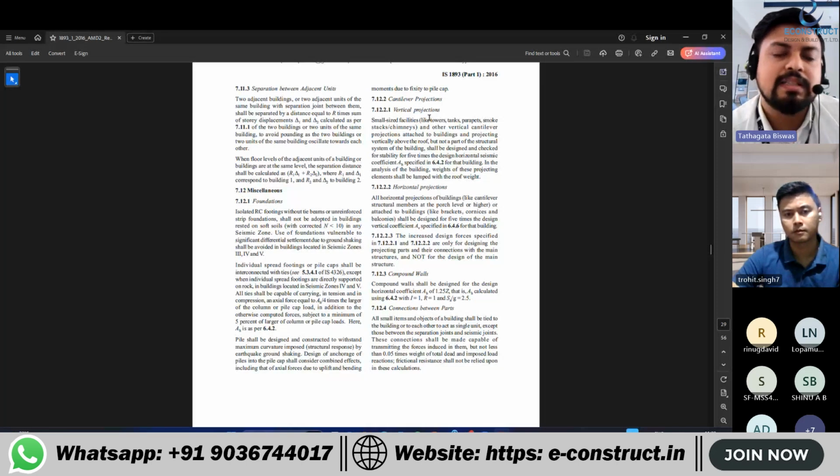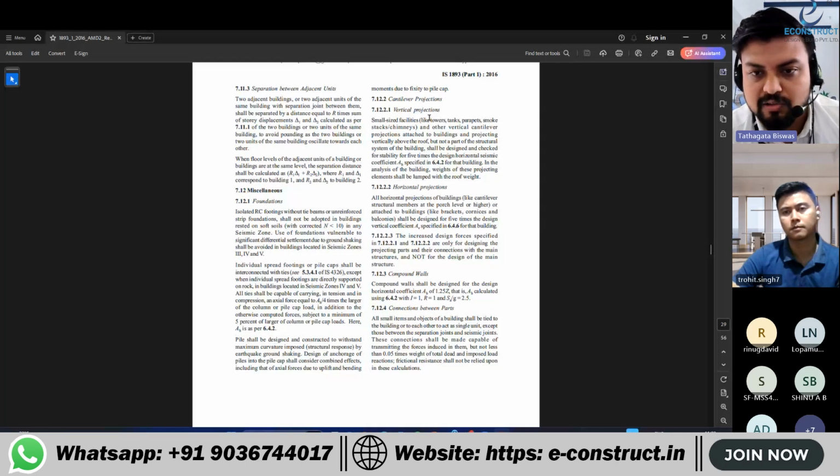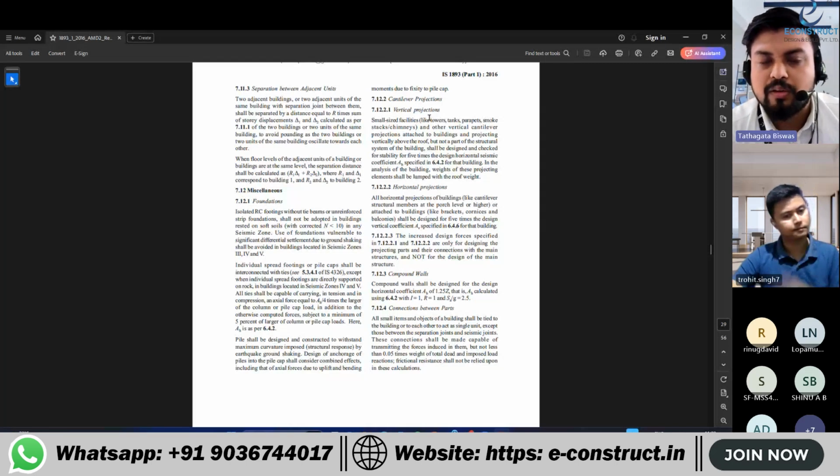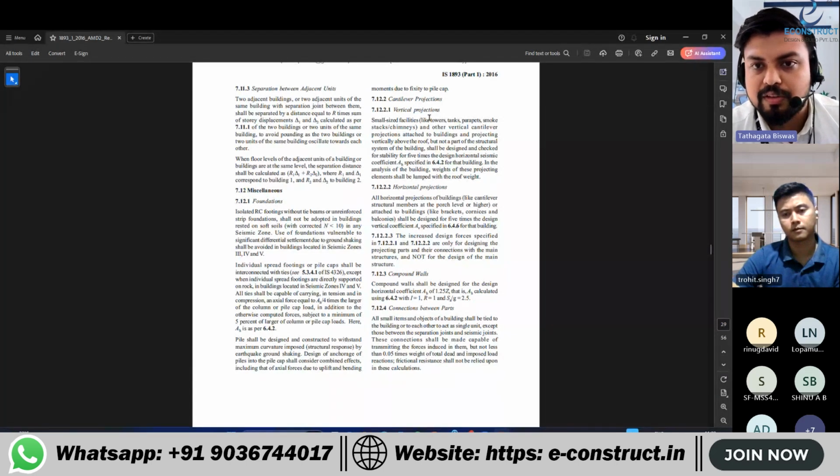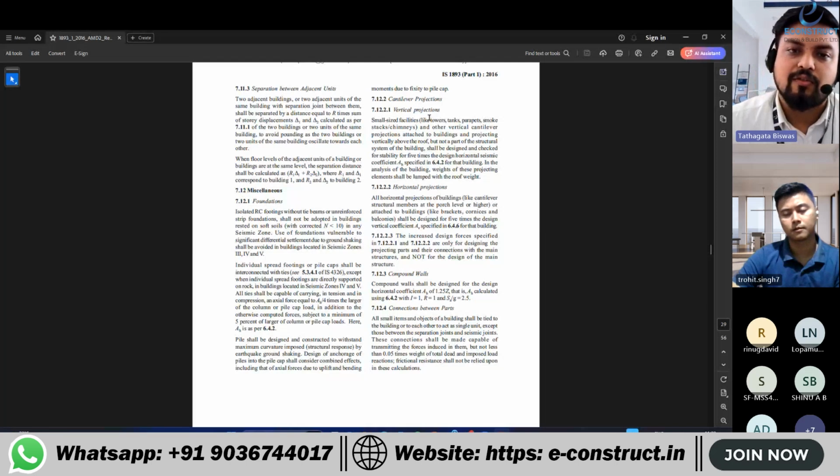But Mivan walls are a separate thing. Mivan walls we are anyway modeling, so for that the stiffness is also already taken. Once we are modeling Mivan walls, we are not considering any load on top of the beam if there is no wall, since we are modeling it that way.